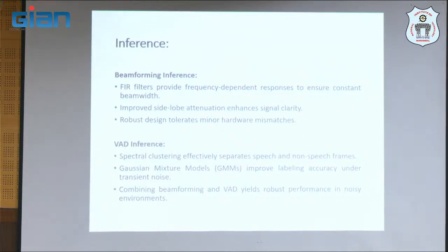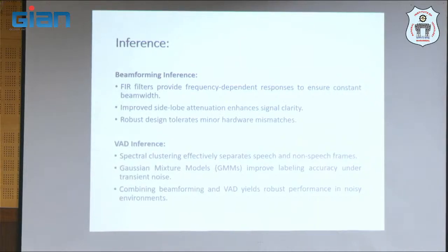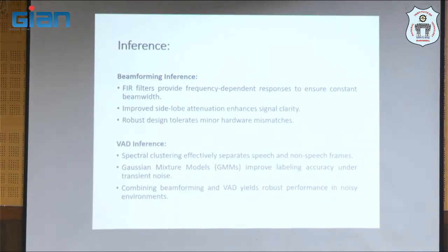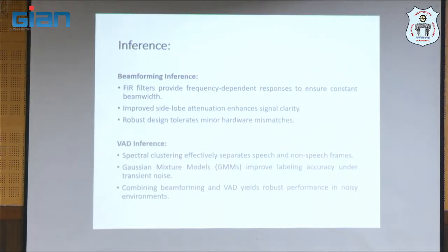By using FIR filters, we can get constant beamwidth, using a temporal filtering technique, that is, creating multiple signals. For higher frequencies, the beamwidth is narrower, so to maintain constant beamwidth we are using the FIR filtering technique.